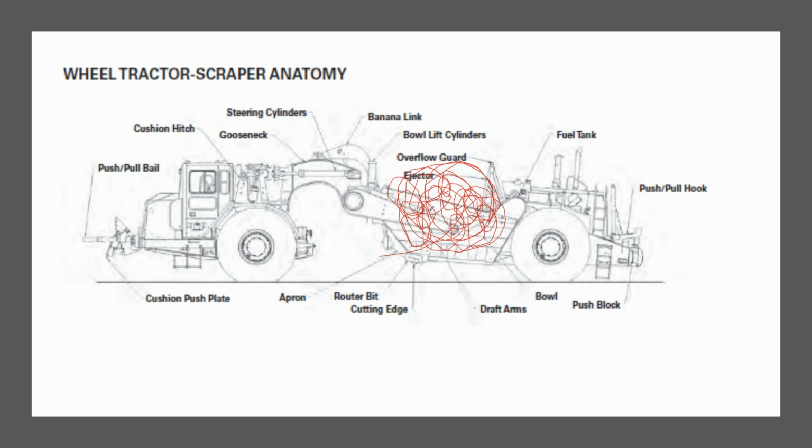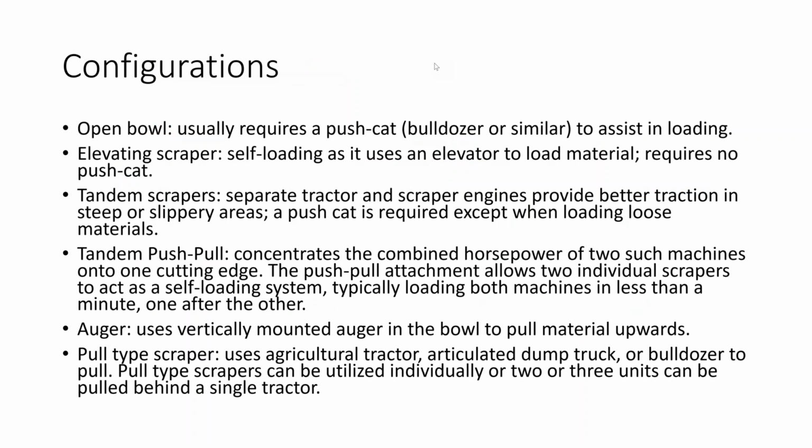Now, it has to do several things with its engine. It has to push the cutting blade through the soil. It also has to haul itself across the site, and then it has to deposit. And so the amount of horsepower that's required to drive across the site and the amount of horsepower that's required to spread the soil is relatively small relative to what it takes to take the 7 or 8 or 9 or 10 foot wide blade and push it into clay and pick it up.